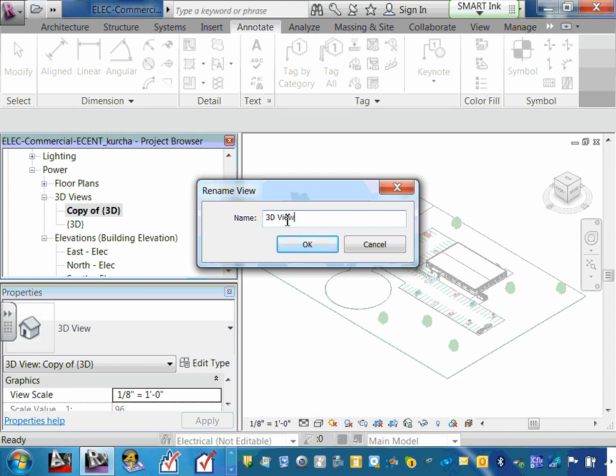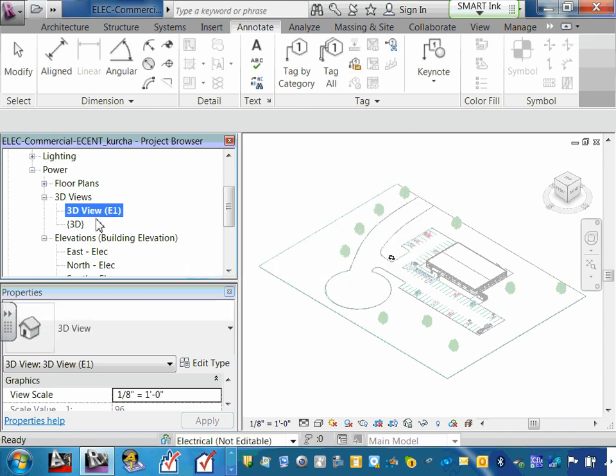3D view, and which sheet would this be in? E1, right? This is going to be the nice picture they're going to put in E1. You can change that one and put in some of the students' work, guys, see that thing there? They put in a rendering, they render and they change. By the way, if you change your mind and you don't like this after you drop it, anytime halfway through the project, it just sucks. I'm going to delete that one. I'm going to go render and put one there, like that one. You see what I mean? These are typical. You can change your mind later on, guys, at any time. Very easy. All right, so E1, click on it, so now this is going to be your E1 job.